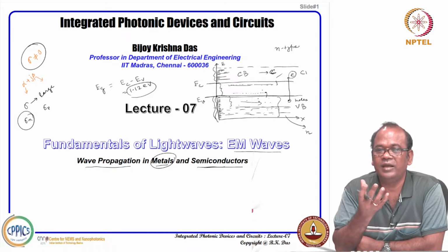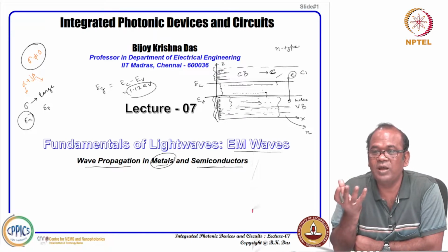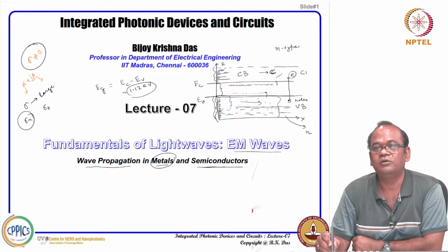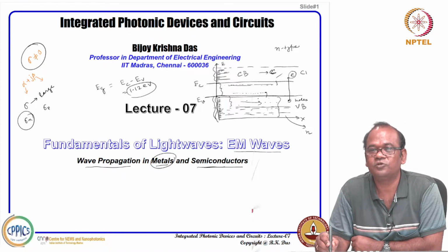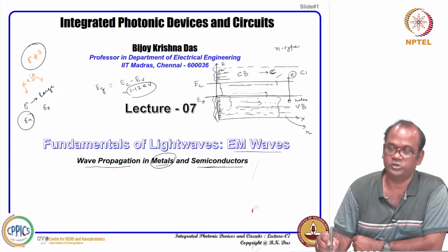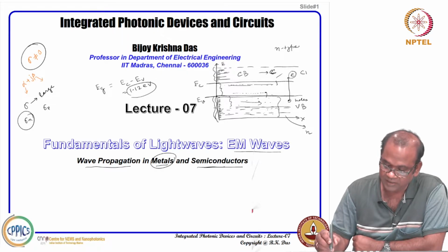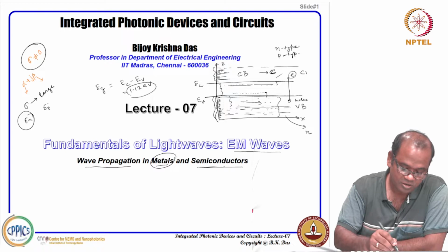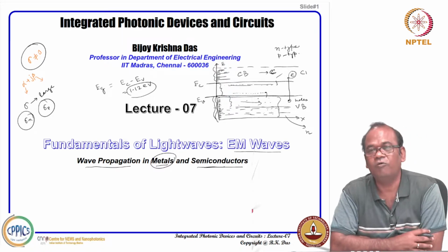That is why immobile negative ions will be created, and in return in the valence band you see empty space. So, some shortage of electrons. So, that is how we can say that those places where electrons are not available are holes basically. So, in that case it will be called a p type semiconductor, and you can also contribute conductivity through holes.